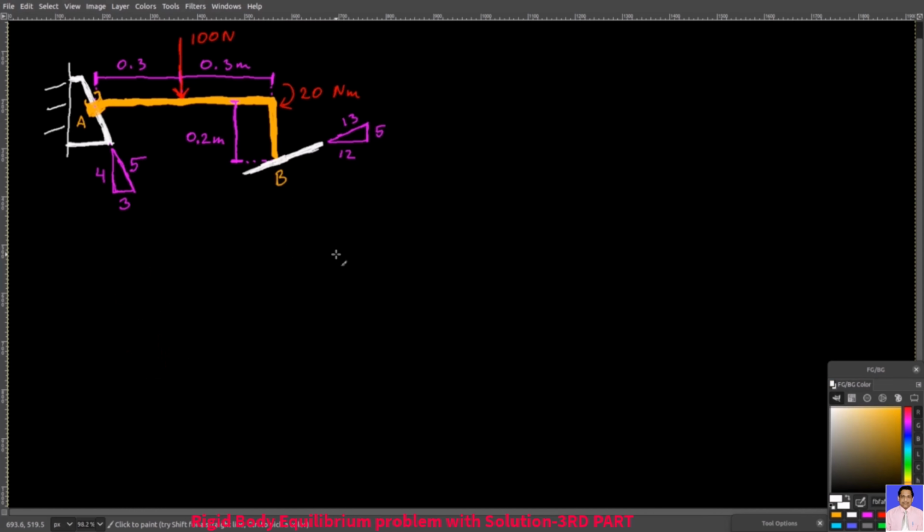Welcome back. Let's now identify and find the reactions at point A and B. Let's first take point A. You have a smooth rod and then the collar can slide along that rod. So translational motion along the rod is not restricted. However, translational motion normal to the rod is restricted, which means that there is a reaction force applied to the structure normal to the smooth rod.